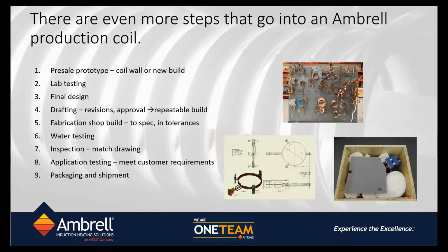What else goes into the coil design process? Well, there are a lot more steps behind the scenes. Because the induction heating coil is copper tube, there are times that induction heating coils get damaged or broken, or a machine runs into it, or sometimes the coil just doesn't work because somebody forgot to turn the water on or bypass some of the safety devices, and the coil is no longer usable.